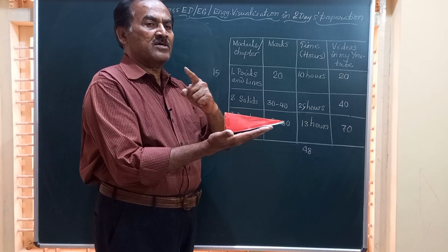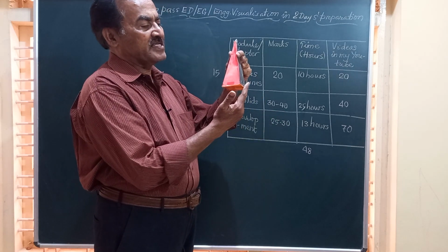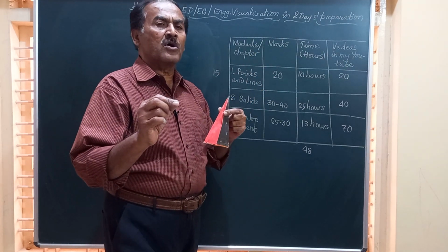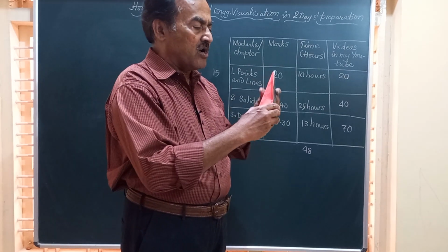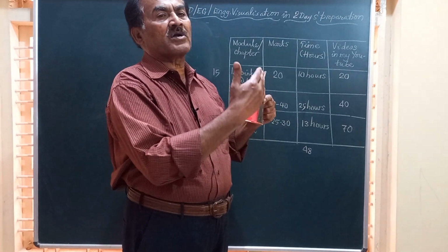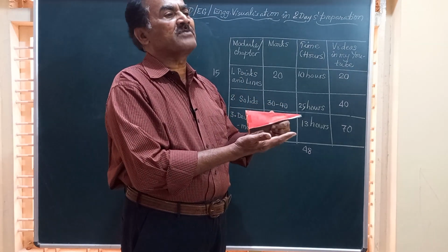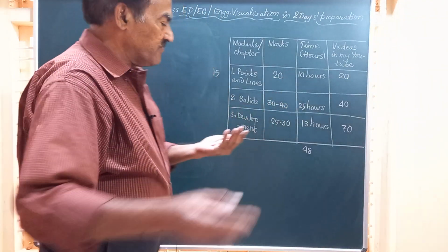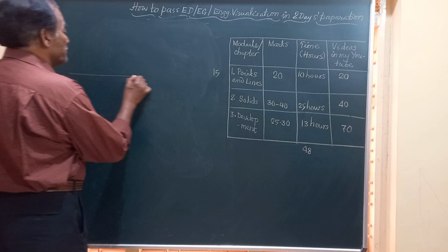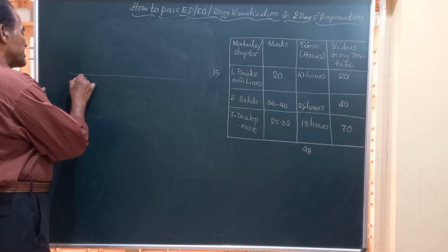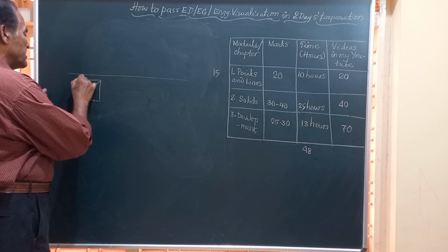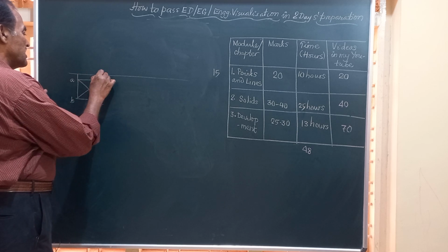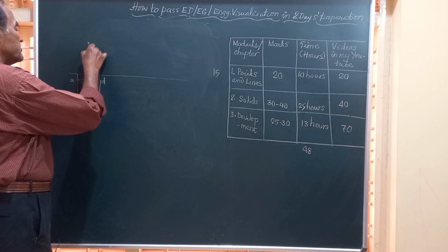So you will be correct only when you take up one of the edges of the solid perpendicular to VP. It is also applicable to all the prisms and cubes wherein on the lateral surface you have got what are called rectangular faces. The same rules hold good. So, friends, initially, for this square pyramid, I am going to write down the top view. That's going to be a square of the given side represented by ABCD, and we have this O. The height of the object will be given.